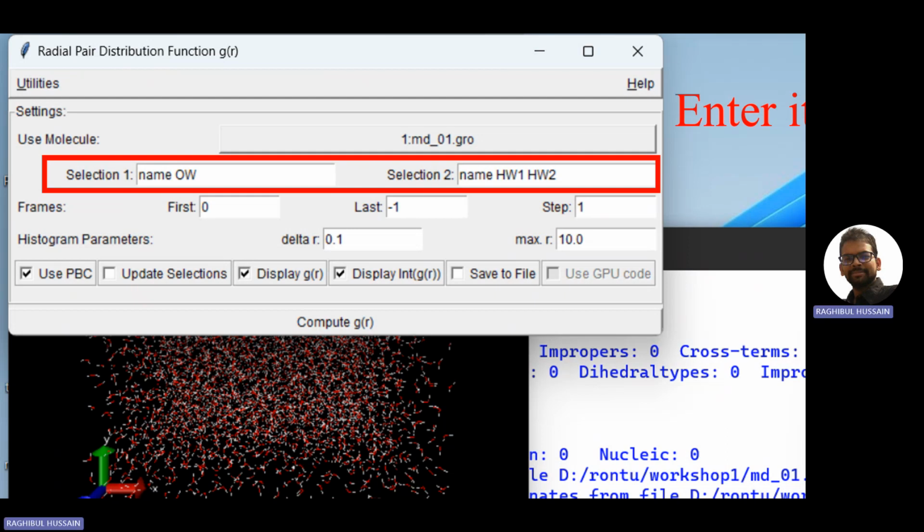That is the atom name. I think you remember when I did it. So in my case, it is NPT g(r) also. Okay, whatever, fundamentally the same. Then compute g(r). Click. Selection one name is OW. Here it is for atom. You can analyze based on molecule, atom, or residue specifically, or you can take serial also. There are several options in VMD actually.